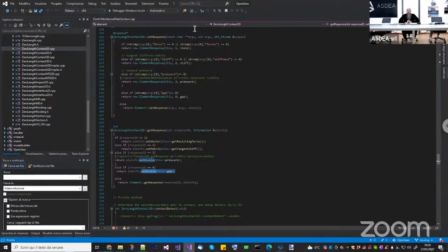Is there any way to include the TCL code already developed for a particular member into the existing model in STKO? I have developed the model for masonry infill, which takes into account the biaxial interaction. However, it is very difficult to draw this model in STKO directly. A lot of zero length elements. Moreover, I can't add it to the input file generated by STKO as the TCL file will not get updated.